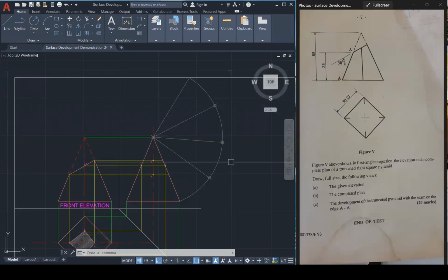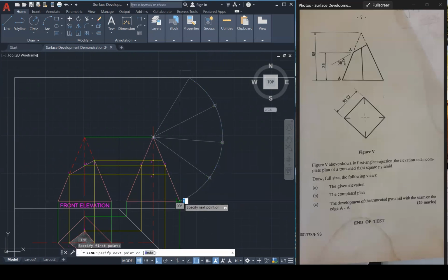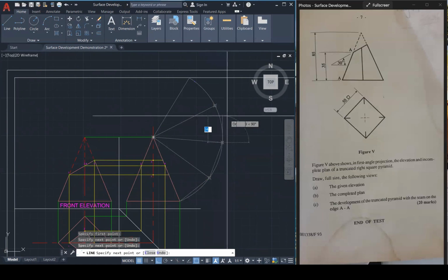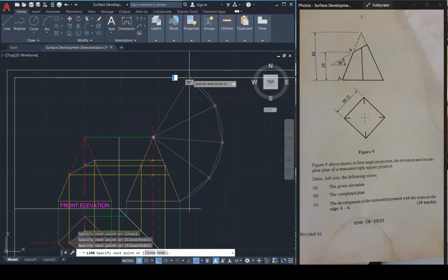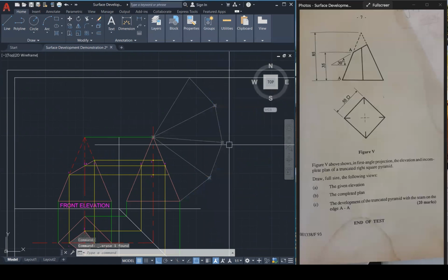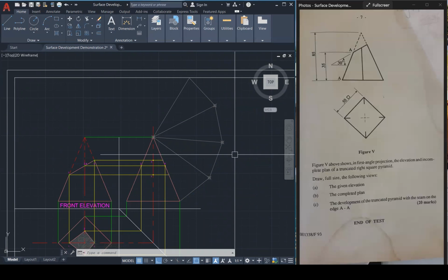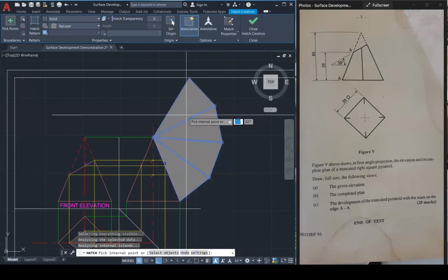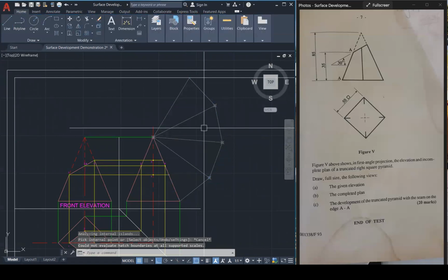But you're probably wondering, why do I have circles or curves as the base? If I were drawing a pure pyramid, this would exactly be the development. You can cut this, and fold them, and I will get back my pure pyramid. However, I'm not doing that. I'm doing a truncated pyramid, so I need to create the tracks for the truncation.